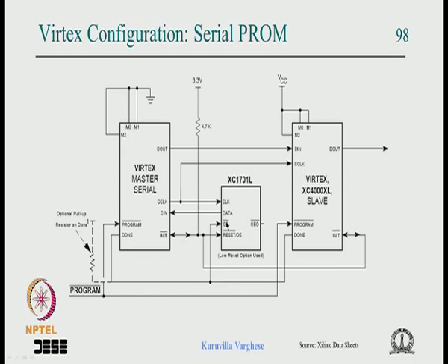Okay, because in an FPGA the main thing is in this PROM, and there is no security on it. The bit stream is coming as it is, it can be easily read. So it will be worthwhile if it can be protected, because mostly this will be some intellectual property of the designer or the company which is doing the design. So what is done in the current FPGAs is that this bit stream can be encrypted using the Advanced Encryption Standard, which is called AES, using a 256-bit key.